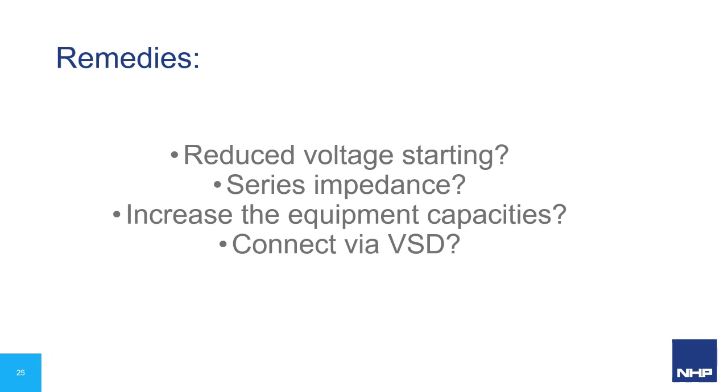They basically are a reduced voltage starting method, which is a smooth transitional way. So can we connect an impedance in the line? Well, you can, but this is similar to a reduced voltage start. A reduction in torque will be the result, and of course, if the impedance remains connected after the start, there's going to be a reduction in the system efficiency. So is the motor really worth the extra money if it can't be returned by electrical efficiencies?